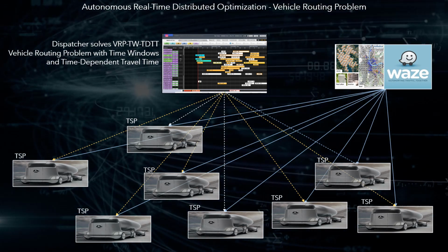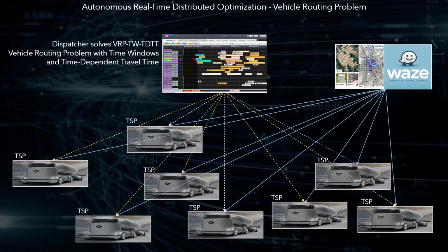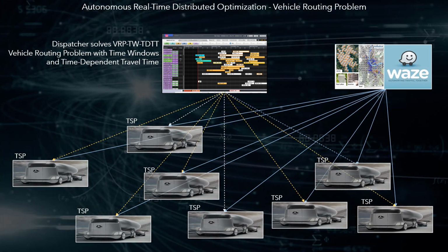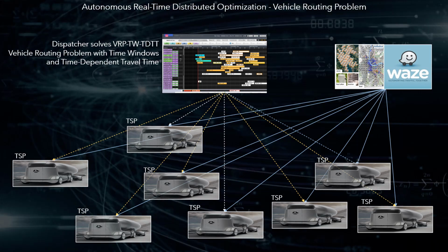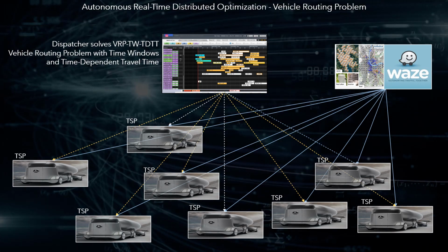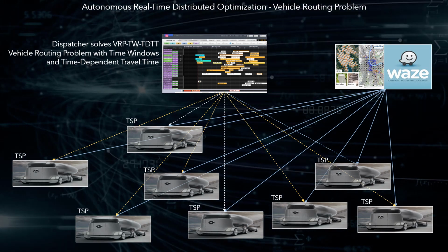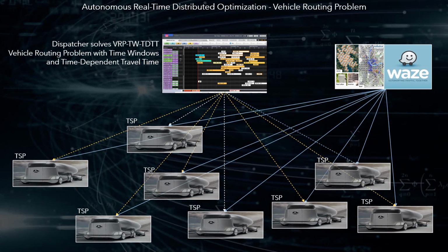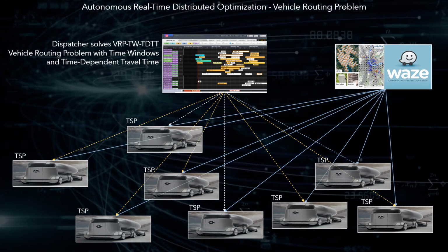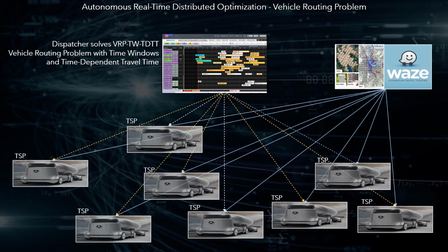The dispatch process can be adjusted as follows. At a certain point in the period, the dispatcher plans all routes solving the routing problem with time windows and time-dependent travel time, taking as input data the latest database updated by all smart metering systems, that is, the trucks, Waze, hydroclimatological, and traffic databases. This process would be carried out centrally, to generate a forecast of the route of each vehicle, to be used that day. Each route must be uploaded to an MSD, a mobile smart device, such as a Raspberry computer, VDO, iPhone, or iPad,